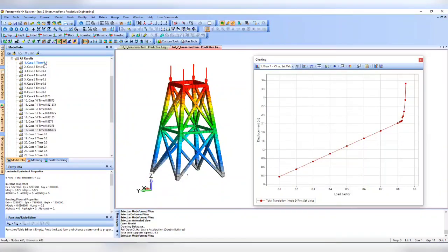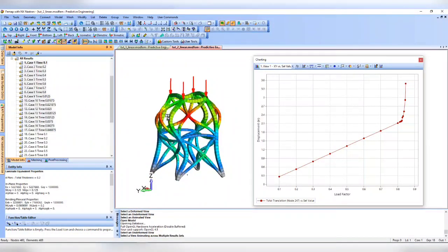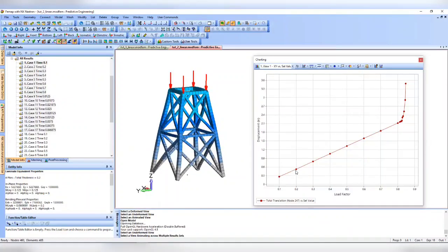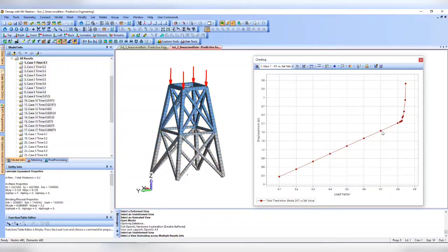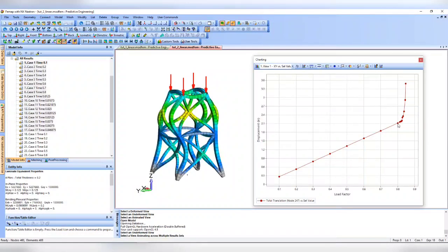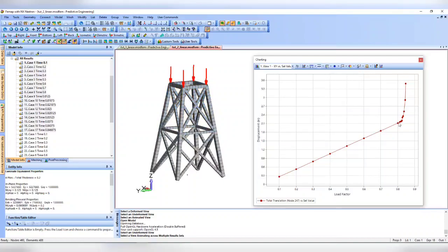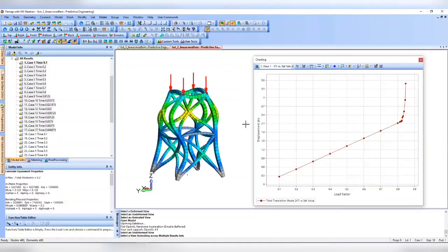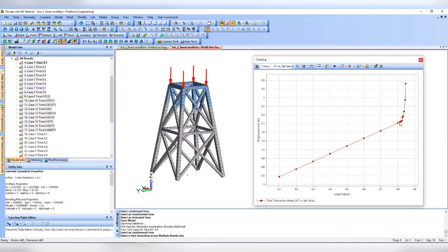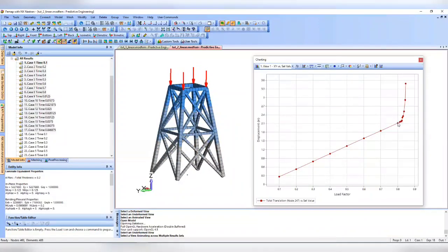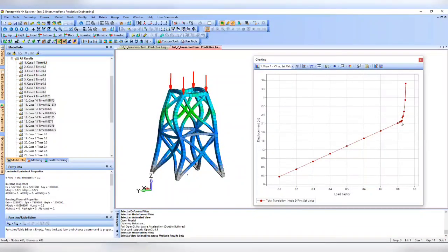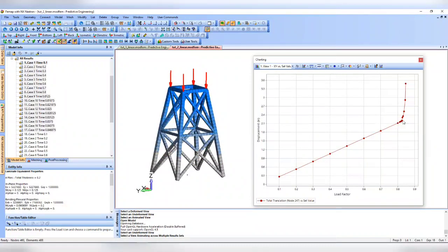What you see is that as we're applying the load in increments of 10, 20, 30, it's displacing in a linear fashion, right? But right at 80, we start to see this weird phenomenon, where this node is no longer displacing in a linear fashion, but it's starting to go asymptotic. That's basically telling us where the system is going unstable. It's going unstable right before it turns asymptotic.